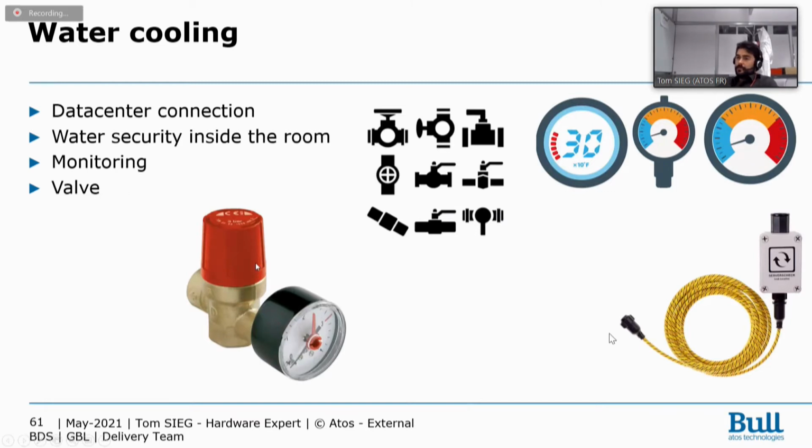And forget the last one, the pressure valve bypass, because of course some systems, racks or infrastructure could be closed, and you don't want to see the pressure increase in the system and break it. So two solutions: a pump with automatic pressure regulation to prevent any overpressure or pipe explosion, or a bypass to be sure that if the pressure increases above a certain number of bar, it will automatically open and protect your installation.